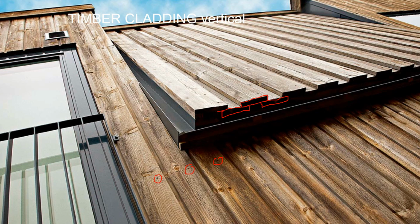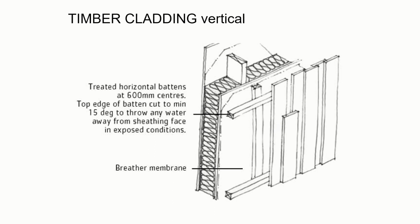And because it's probably larch, this timber here, so it's got quite a rough surface, we don't see the fixings. The board isn't as strong as an oak board, so it's not going to pull those screws out. It's not going to move about as much, or if it is, it's going to be held by the screws. So the board-on-board cladding is quite a common way to do vertical timber cladding. We've got the front board at that point, and then we've got a back board running behind it, and there's an overlap there of about 20 millimeters, something like that.